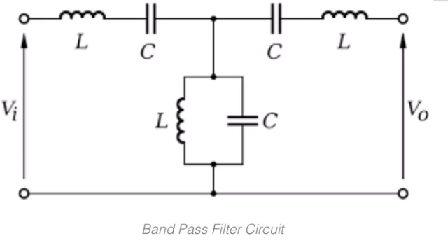Okay, this is the circuit diagram for the band pass filter. So here the band pass filter is not ideal. That doesn't mean it attenuates every frequency outside the preferred frequency range. Particularly, there is a section just outside the proposed passband where these frequencies are stopped. However, these band pass filters are specified with attenuation for every octave of frequencies. So, in general, this filter bandwidth can be defined by the upper frequencies as well as the lower frequencies.